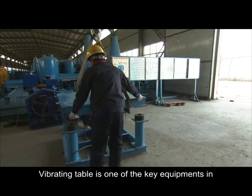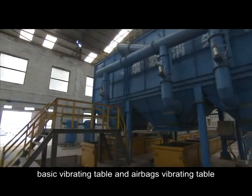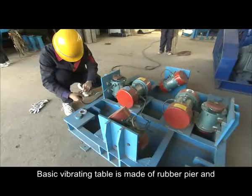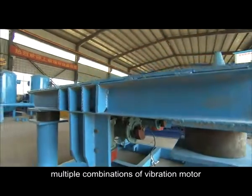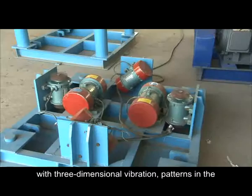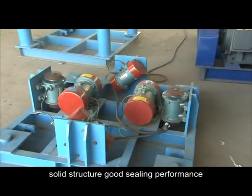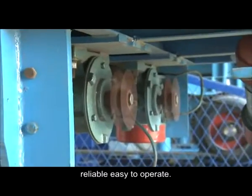Vibrating table is one of the key equipment in lost foam casting. Generally divided into basic vibrating table and airbag vibrating table. Basic vibrating table is made of rubber pier and multiple combinations of vibration motors. With the three-dimensional vibration, patterns in the box are filled with sand with no dead corner. Solid structure, good sealing performance, reliable, easy to operate.